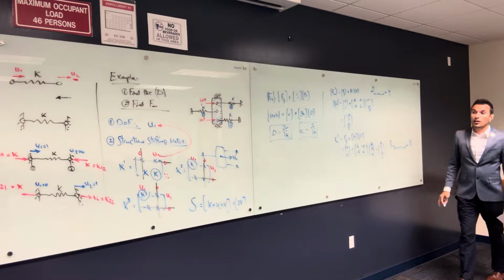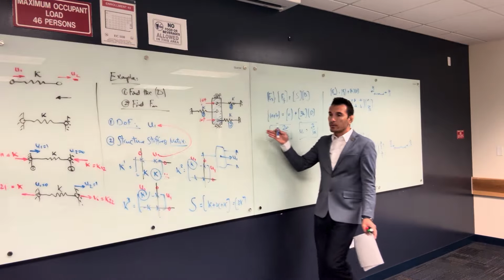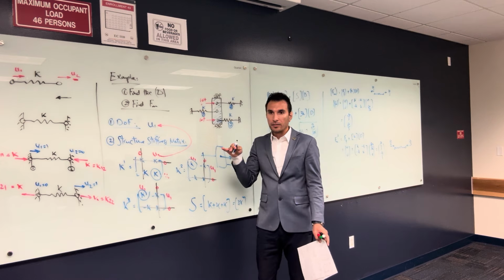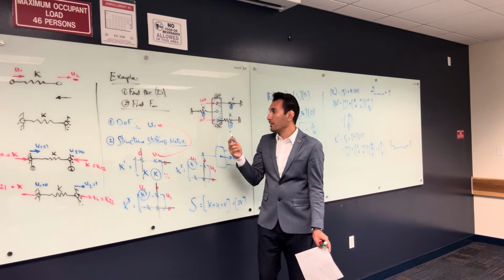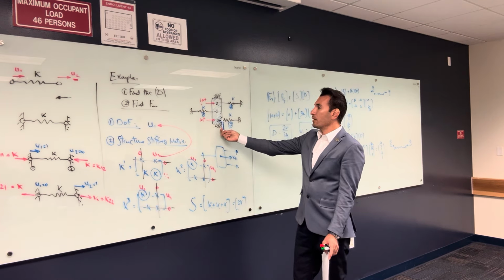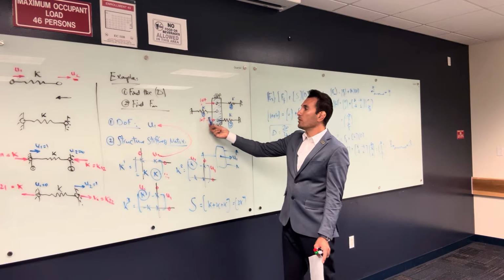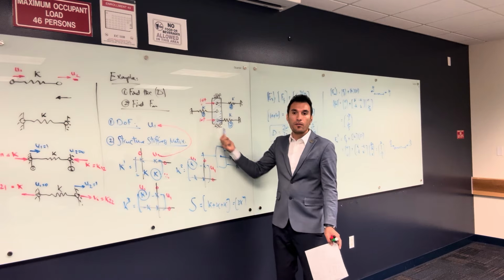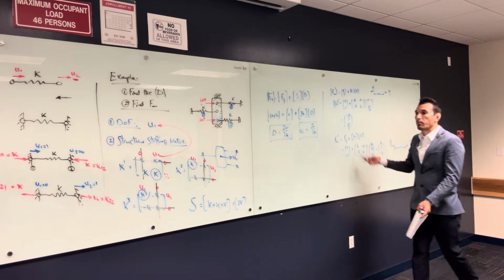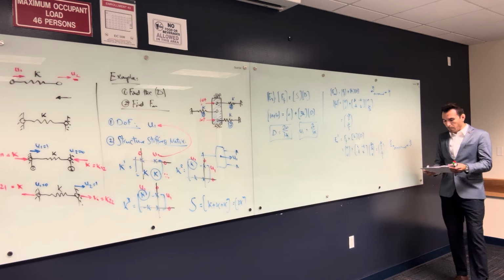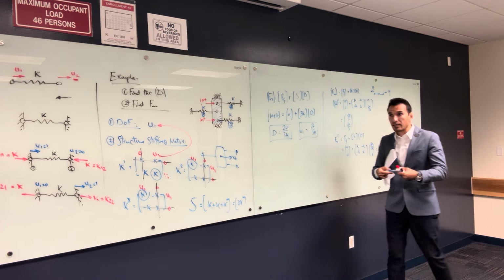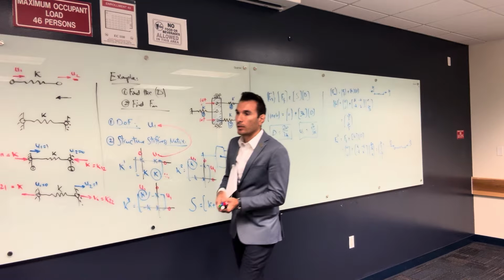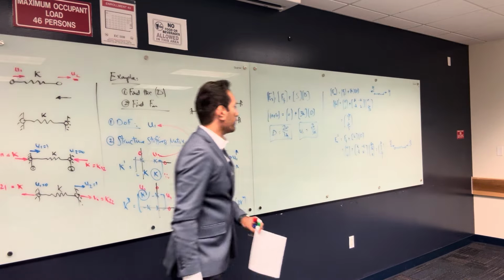Alright? So look, actually we can solve this visually in the first place, without doing all that. We found out that this is going to be 20 over 3K, and then you multiply this by K, so it's going to be 20 over 3. But this is how you solve it mathematically using the stiffness method. So let's actually make this complicated so that we cannot solve it visually.